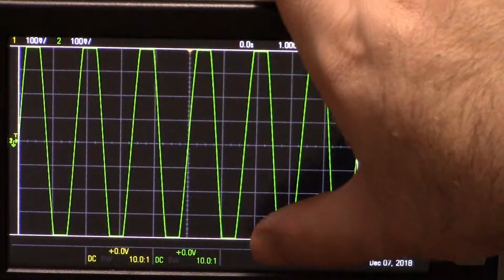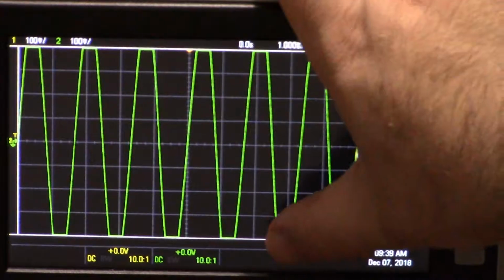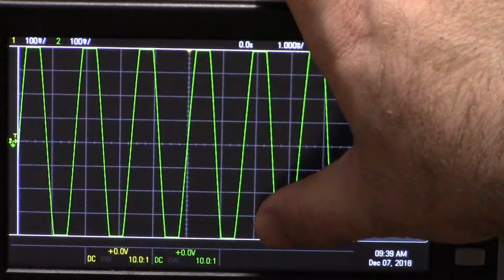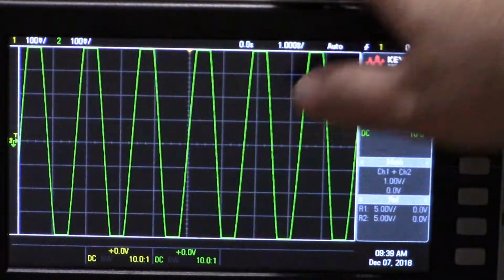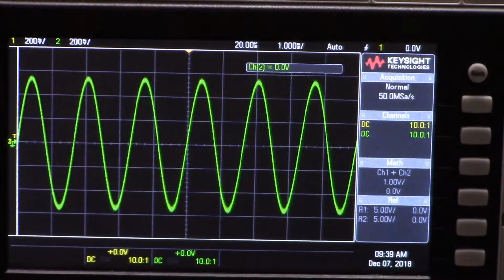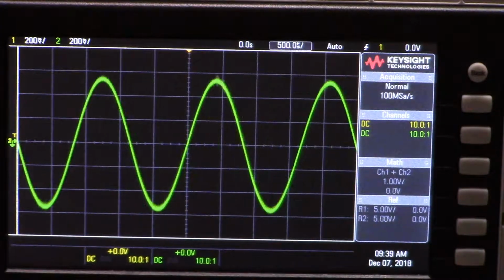But also, the audio file uses the full amplitude range, -1 to 1. The VLC volume is at 100%. The system volume is at 100%, so it's sending the signal completely unadjusted. So now, let me shrink down until I can see it. Make sure it's centered, make sure the time is centered, and now we can see our nice 600 hertz sine wave. We can verify the wavelength.